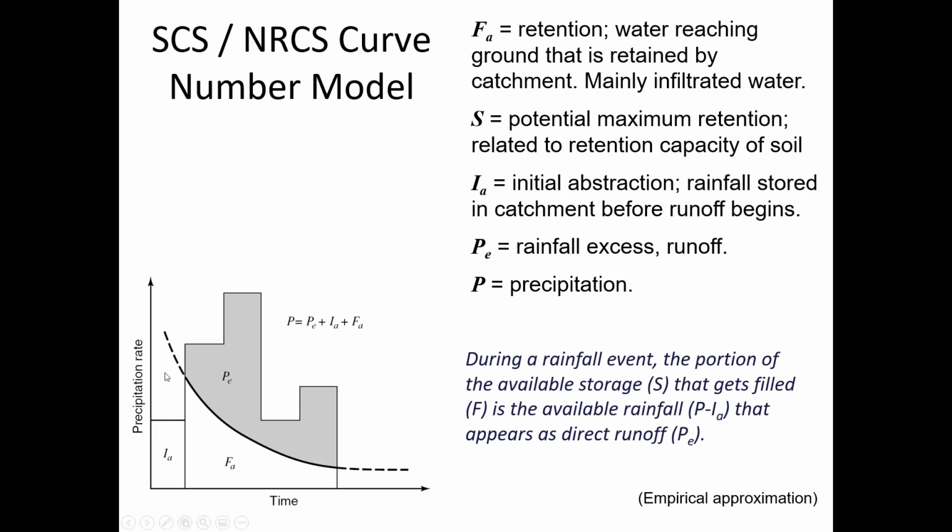So to the left of this curve, all of the water has been absorbed. And it's only when you're to the right of this point of intersection that there's leftover water beyond what the ground is able to infiltrate. So that's why this dashed line, it was when it was the potential infiltration. It wasn't yet an actual infiltration rate because it could have absorbed more water than it did. But there was only this much rainfall.